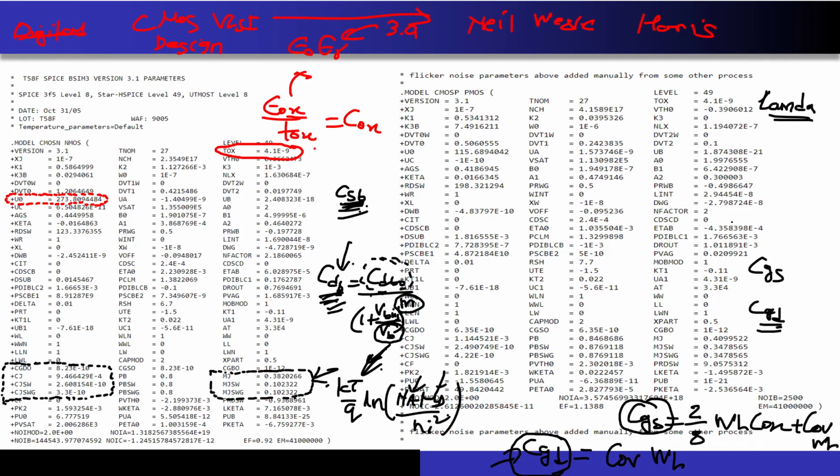Once you know this, then remember the parasitic capacitance at the current mirror load that sir had given, correct? It was looking something like 2 times CGS, correct? Plus 2 times CdB, something like this. I don't remember exactly, but you can easily figure this out, correct? Then you should substitute these values over here. After that, you will get the value of parasitic capacitance inside the OTA. And once you know this value of CP, after that, you can calculate the values of poles and zeros that are actually getting contributed by the